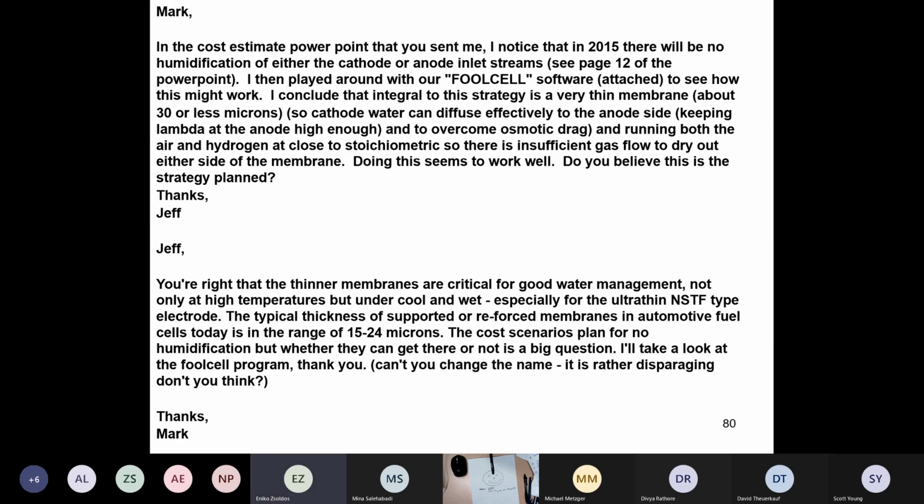Yeah. Okay, thank you. I would add to that, the solid oxide fuel cells are even worse when it comes to restarting them, because you have solid materials and the expansion coefficients have to match up. So if you cool and heat up again, it will crack the different layers. And so it's really good for stationary constant power kind of running. I see. Thank you. That's good, Ron. Thanks for that comment.